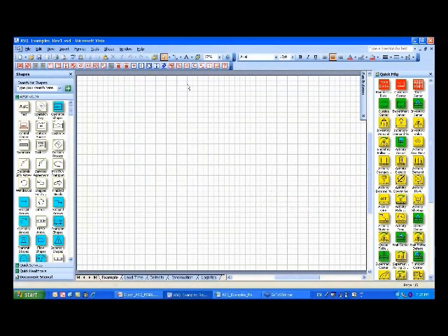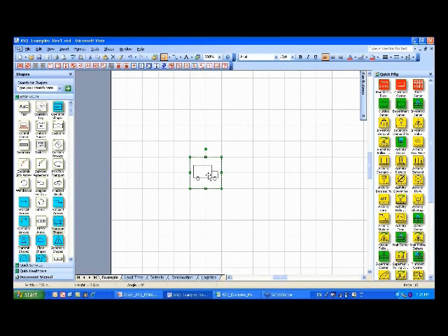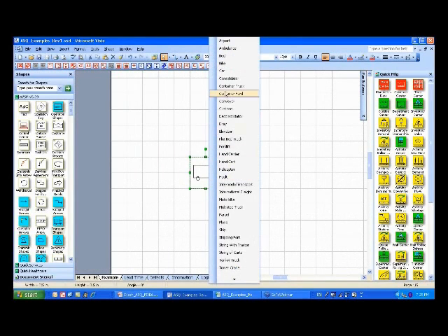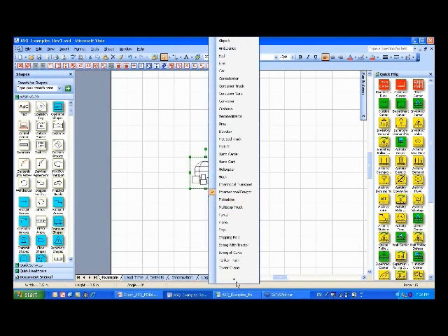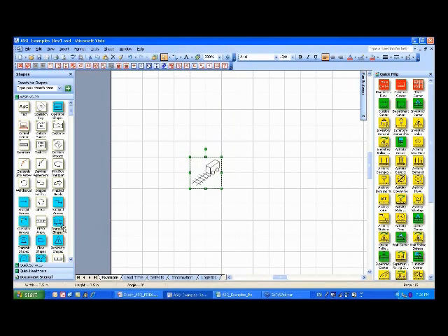I've pulled up the eVSM software, which is a little add-on to Visio. Within it, we've got all the value stream mapping icons. For example, things like the transport icons I talked about. If I right mouse click that, you can see there are other transport types available, you know, international freight, train, etc. The blue icons basically are icon families.